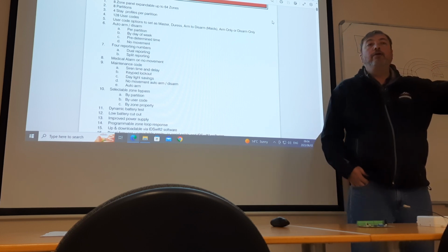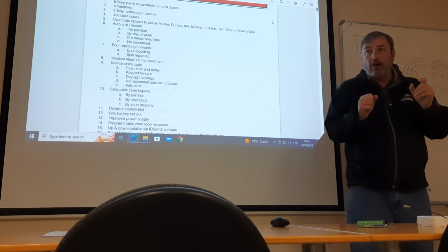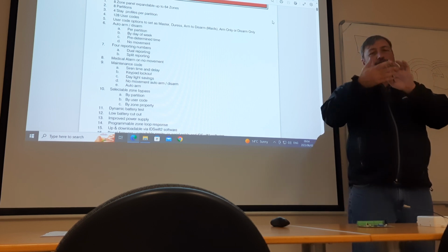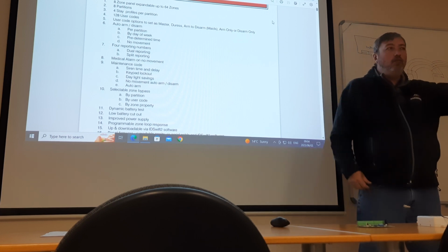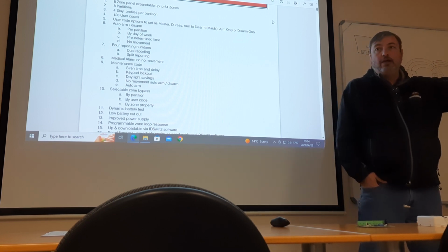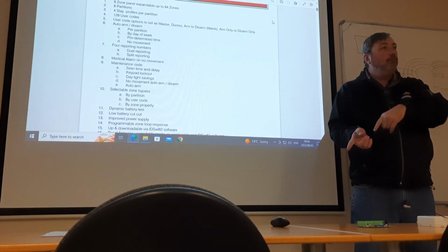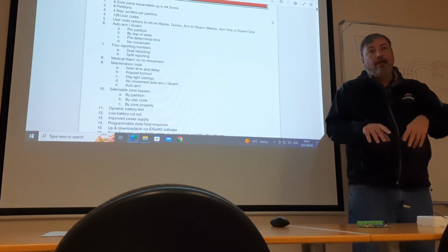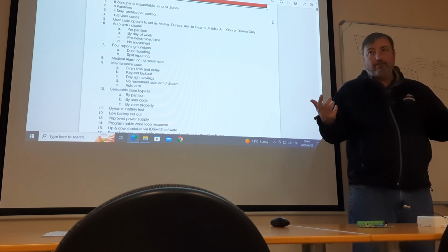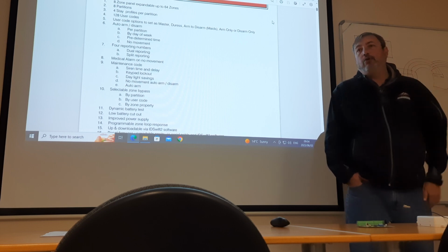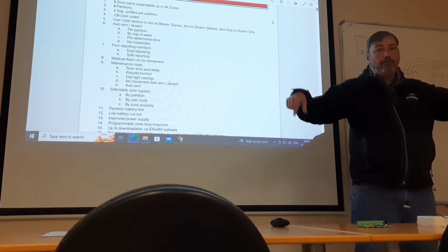Then you're going to put those beams on a different partition, because then you can set up what they call a stay profile. You can have up to 4 different profiles. I can put the outside beams on, say, partition 2, and I can arm them, but the ones inside will still be disabled. Only when I go to sleep will I arm the ones inside the house as well. Stuff like that. Another example of why you would use partitions is, let's say there is a business park, like a big complex, and there are a lot of companies inside this one building.